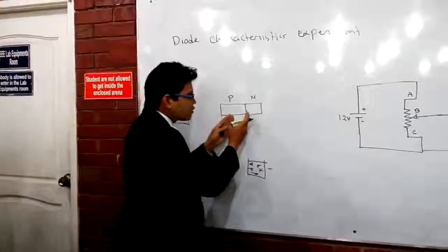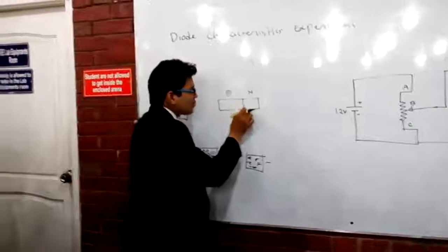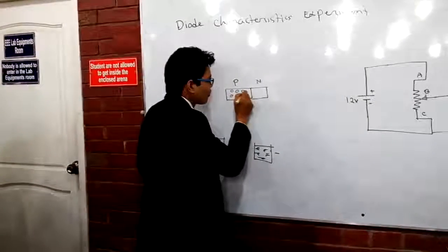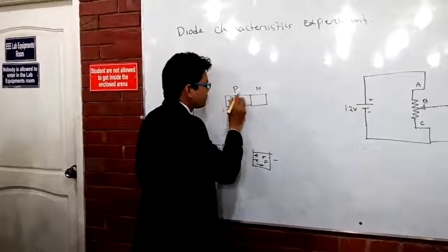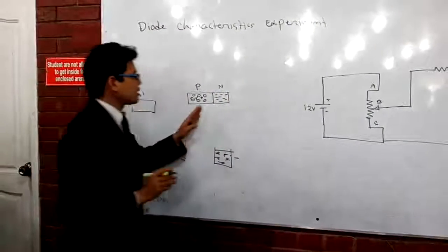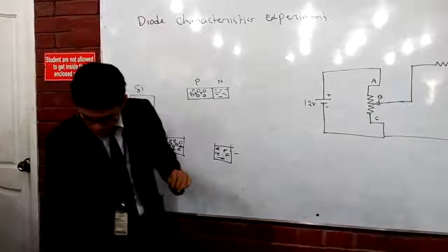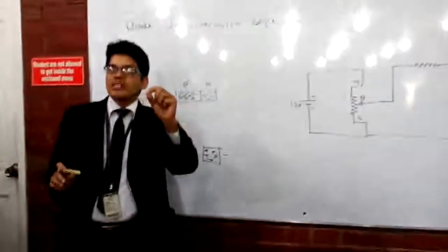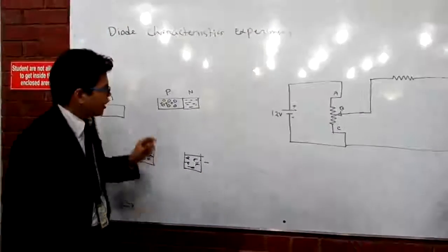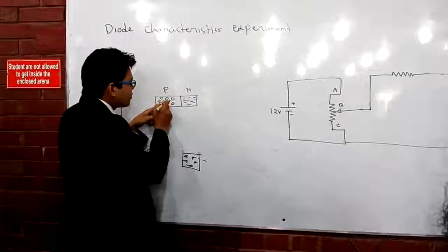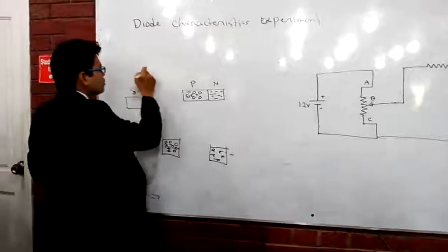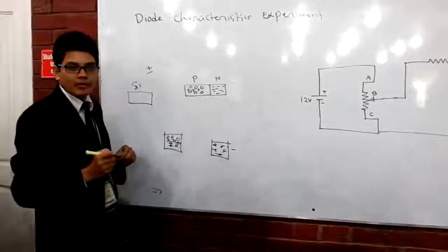Once you add these two things up, there is a junction point, right? There are holes of positive and electrons of negative. So under normal state, what happens? This PN junction is right now under normal state because we are not providing it with power. I talked about this in the first class: two oppositely charged particles attract each other.